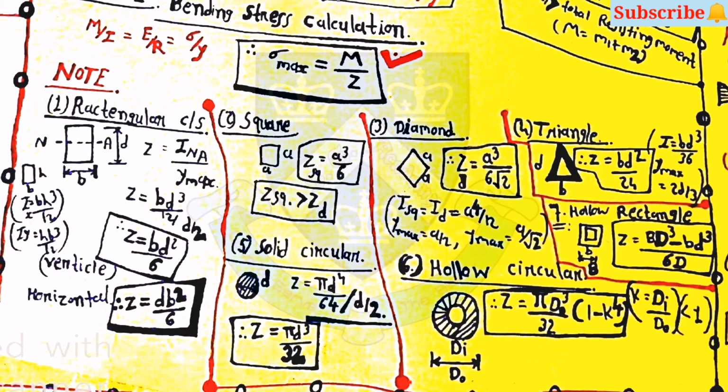And then the fourth one is for triangle, Z is equal to B D squared by 24. For hollow rectangle, Z is equal to (B D cube minus b d cube) by 6D. And for solid circular, Z is equal to pi d cube by 32. Then for hollow circle, Z is equal to pi d cube by 32 into (1 minus k raised to 4). Here k is equal to d i upon d naught, which is less than 1.